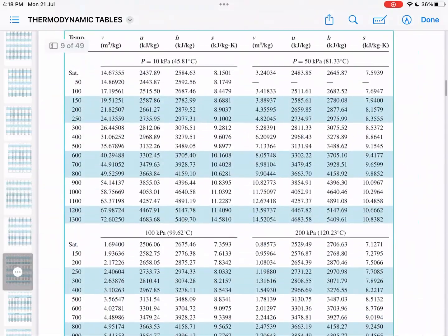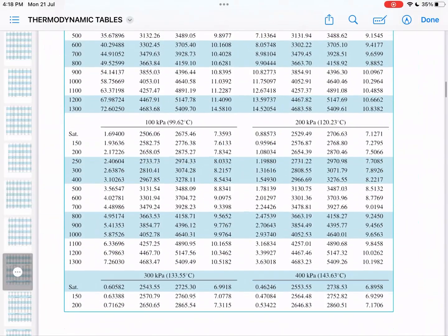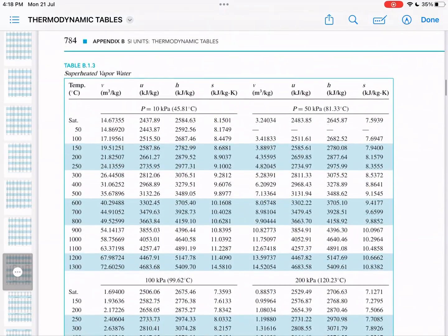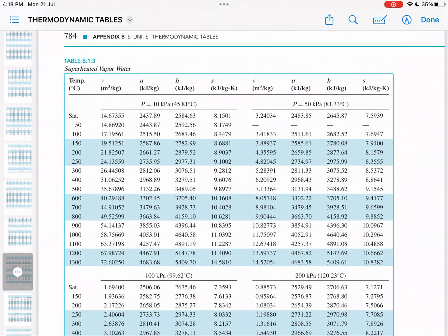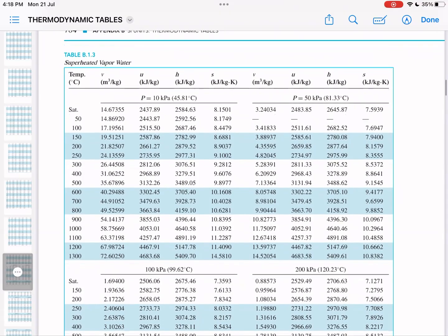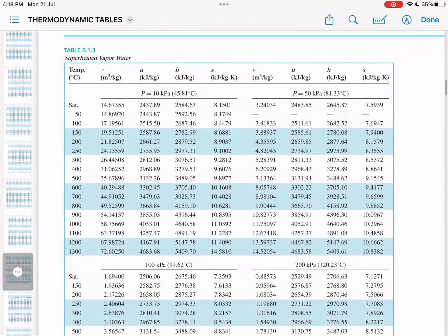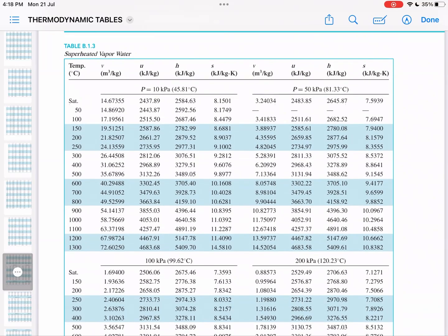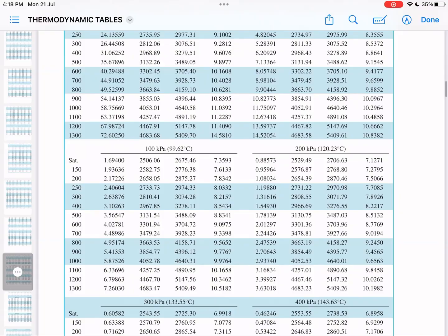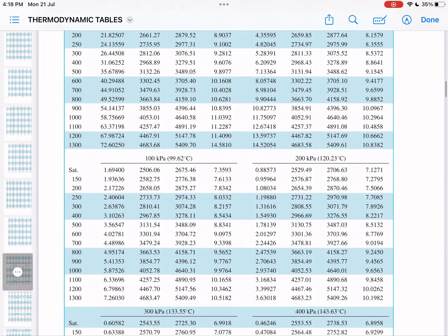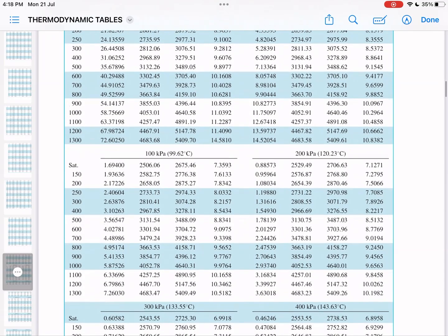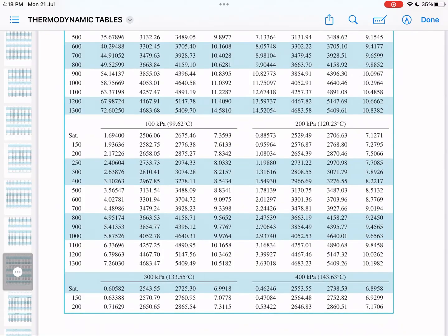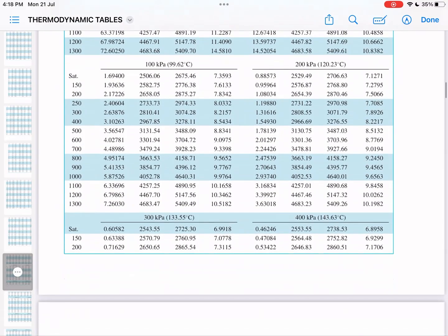and if we see our specific volume needs to be 0.5. So at 10 kilopascal, 200 degrees Celsius, it is 21 point something. Then it goes down to 4 point something at 50 kilopascals. Then it goes down to 2.4 something at 100 kilopascals. Remember, we are looking at everything at 200 degrees Celsius. So at 200 kilopascals, it goes down to 1.0 something.